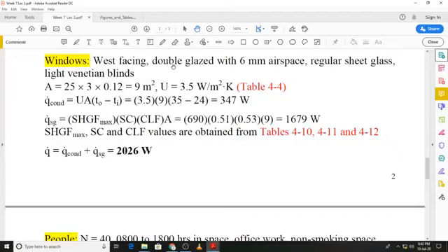So you can see that in the first column we have the wall type, then the orientation is also given, and the other thing that we need is the solar time. The first set of data is for wall type G. We have wall type F, so we scroll down to the appropriate wall type, that is F over here, you can see, and that will be the set of data that we will be using. So we have wall type F. The orientation is that the wall is west facing, so that's the column that we will work with, and the time again is 1400 hours.